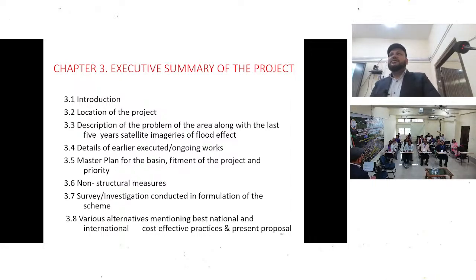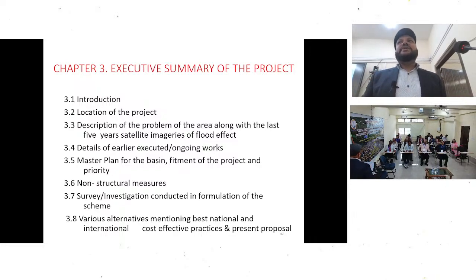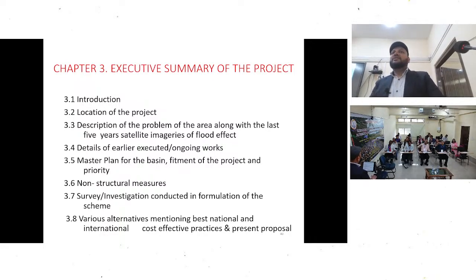Floodplain zoning, flood forecasting, early warning system is there, and survey and investigation conducted in the formulation of the scheme. Various alternative means we have to discuss, we do not just choose one thing. We have to discuss what should be required, whether an embankment is required, or only laying porcupine is sufficient, or only putting geobags is required, or only wire crates is sufficient.